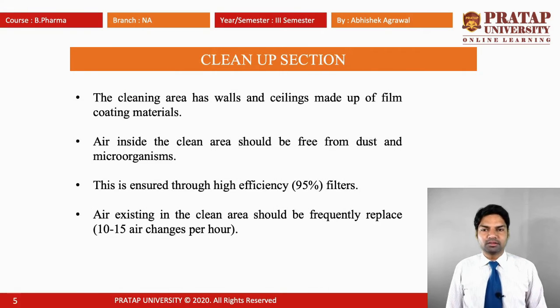In the cleanup section, the clean area has walls and ceilings made up of film coating materials. The air inside the clean area should be free from dust and microorganisms. This is ensured through a high efficiency filter, approximately 95%. The air in the clean area should be frequently replaced, with 10 to 15 air changes per hour.